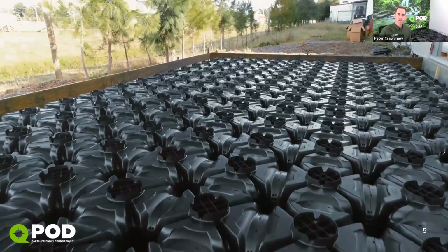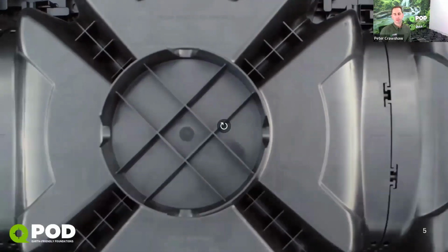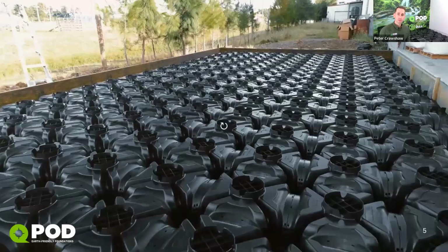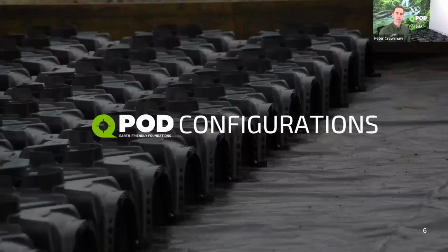But yeah, essentially it is a modular system. It's got the built-in mesh spacer on the top here, and that gives you accurate mesh placement when you're placing that mesh down. And then obviously very stable when you're coming to pouring all that concrete and putting it together on the site. We'll have a look at a couple of configurations of the QPOD. It is one system of a bunch of components that come together in different ways.